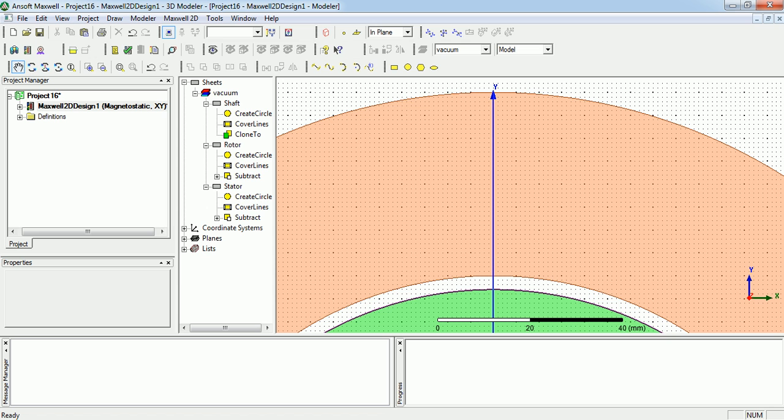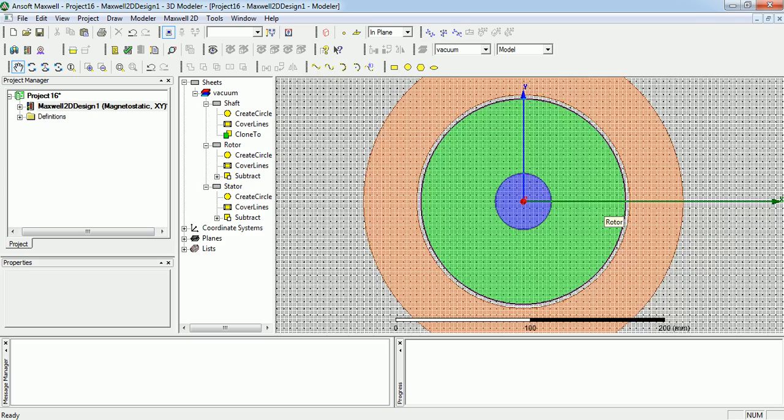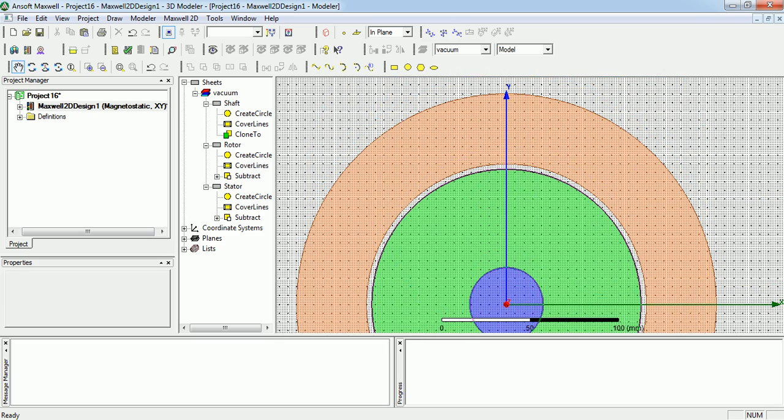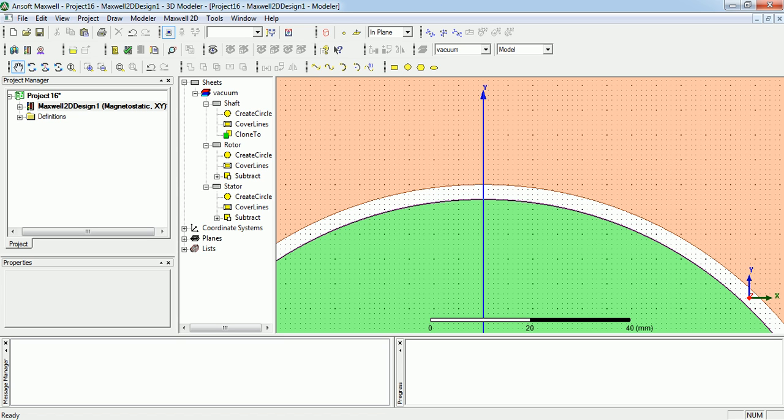If you look at the original figure, you have the global origin at the center 0 0. We can offset your origin temporarily to a different location and thereby create a temporary or a new coordinate system. So that is how you manipulate the location. Please remember these two things. Selecting the location is done through changing the origin, and accurately providing the dimensions is accomplished through changing the grid settings.